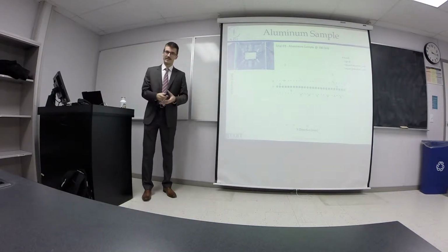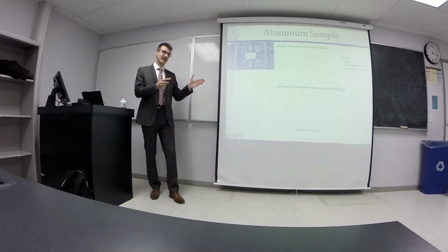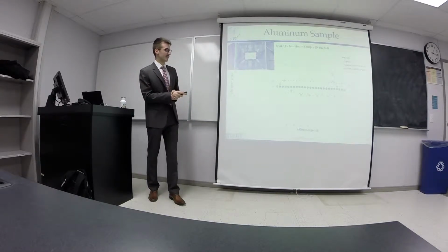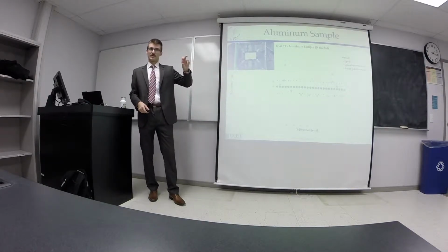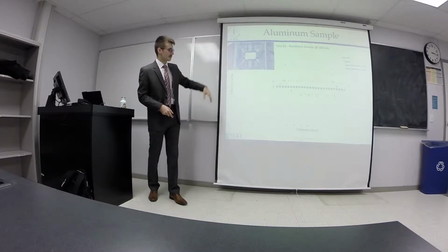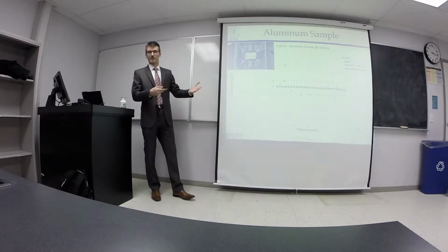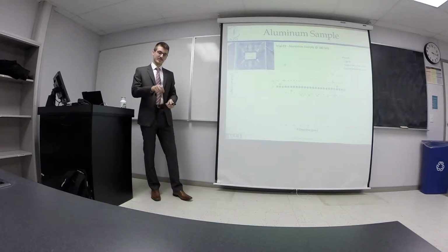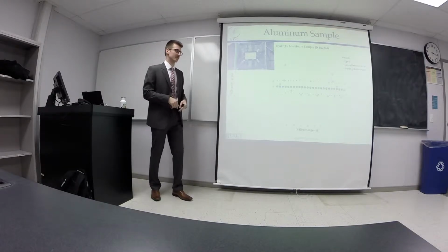So, verifying that this design is useful and works. Sample 1 is an aluminum sample. It's not the same one that I used in the proof of concept, but it's the same material. You can see it's 180 kilohertz, same optimum frequency, and it's a little picture of what it looked like. And the black dotted lines show the actual limits of detection with that diameter that we talked about earlier, 5 millimeters. So any points that essentially fall within this area can be considered as something indicative of a crack or a flaw in the sample. The ones here that seem to fall a little bit short, you can essentially attribute this to human error when actually measuring these things, because you're just trying to recollect where exactly this probe signal was generated.